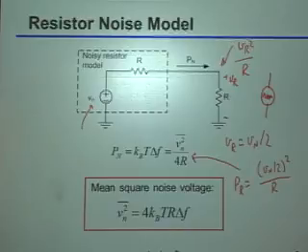Okay, which of course, if you do some very simple math, just tells you that it's Vn squared over 4R. Okay? So if you basically just take that, we only put this resistor in the first place to figure out how much power you could actually extract from the resistor. You say, I'm now going to set that to the maximum power I could extract. You can quickly then calculate that the noise voltage variance is just 4kTR times delta F. Okay? And the factor of 4 here just came because of this voltage divider that we had. The R just comes about, obviously, because of the matching that we were doing. Okay? Is this clear to everybody?